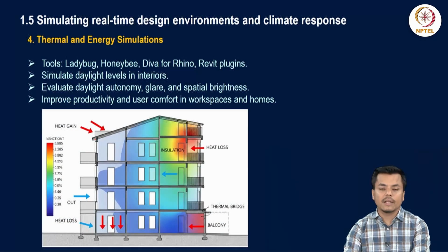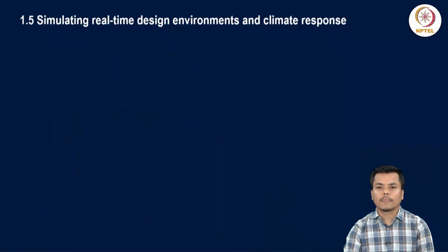The next is thermal and energy simulation. Tools like Ladybug, Honeybee and similar plugins are required for such analysis. It simulates daylight level in interiors. It evaluates daylight autonomy, glare and spatial brightness, improves the productivity and user comfort inside the workplaces.